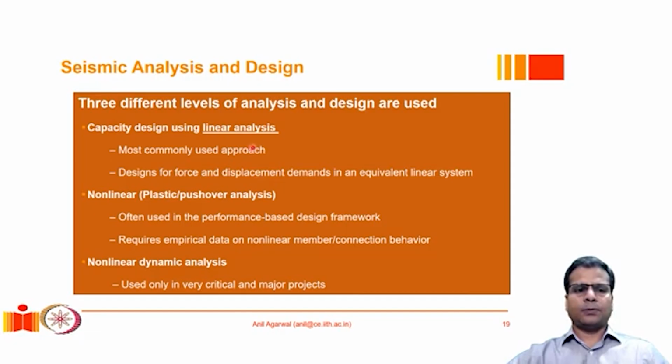In this approach, the advantages are that this is a simpler approach. It does not require so much computational power because the analysis is all linear, and we do not need very accurate constitutive relationships and connection behavior, etc. Whatever models are easily available for connections can be utilized because the analysis in general remains elastic.